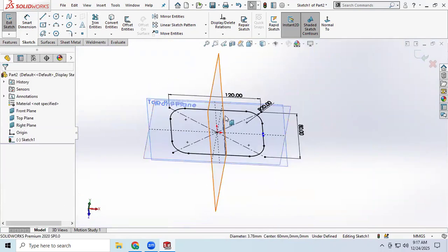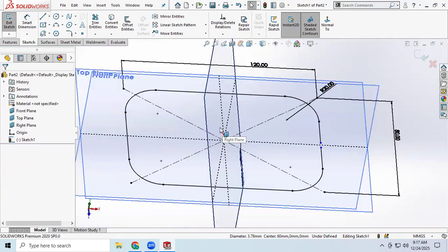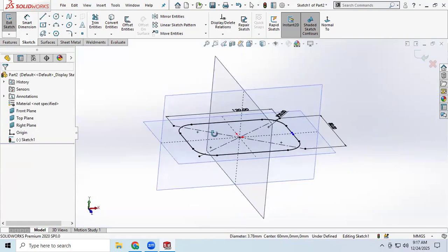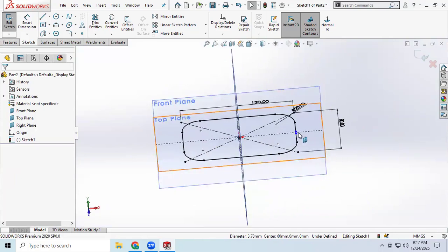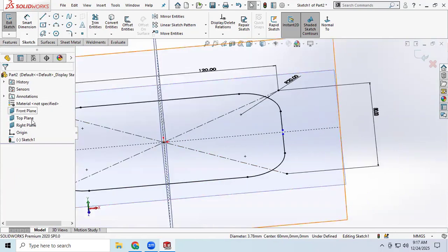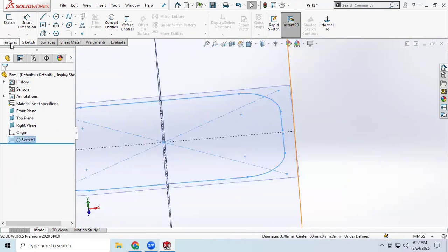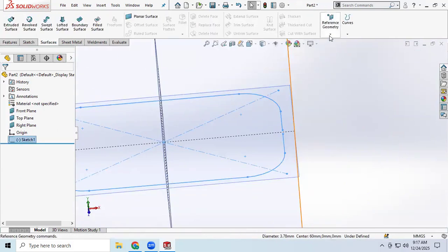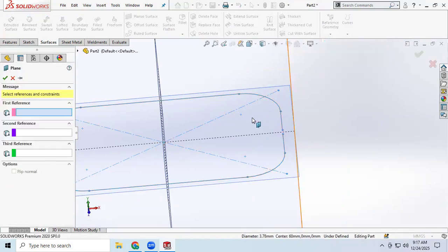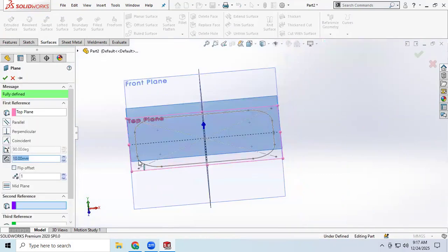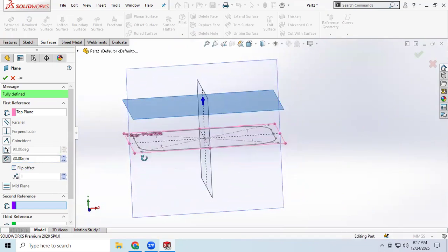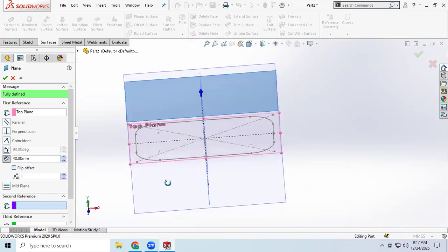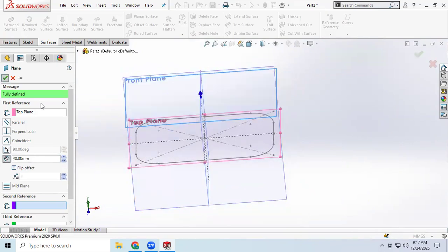After that, for the lofted, we need 2 sketches. Without 2 sketches, I can't do it at all. I can also talk about the lofted features and surface model already. Then, once I go to the existing sketch, select your reference geometry here. Just select it and click on it, and then this will be a reference geometry. 30 mm, 40 mm, whatever you want to do here. I just use this as 40 mm and click on OK.